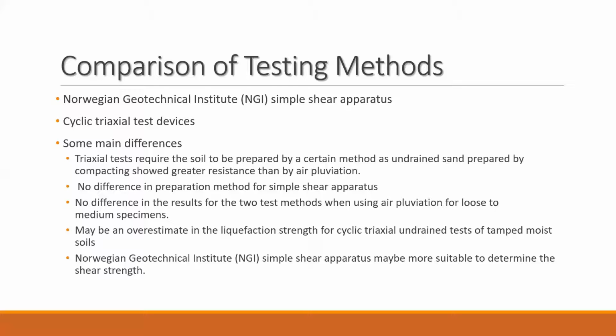There was also no difference in the results for the two test methods when using air pluviation for loose to medium specimens. There may be an overestimate in liquefaction strength for cyclic triaxial undrained tests of damp to moist soils. Therefore, because there was no difference in the method for simple shear apparatuses, we can see that the simple shear apparatus may be more suitable to determine the shear strength.